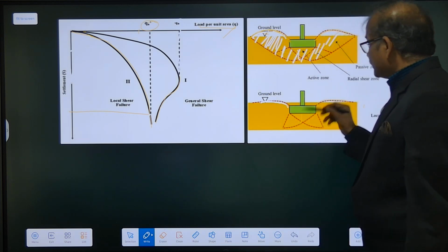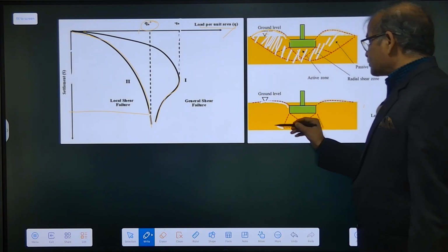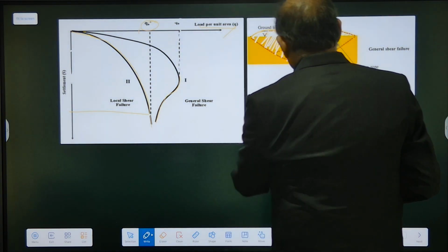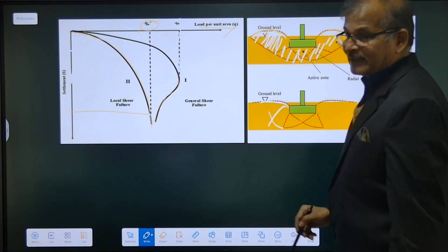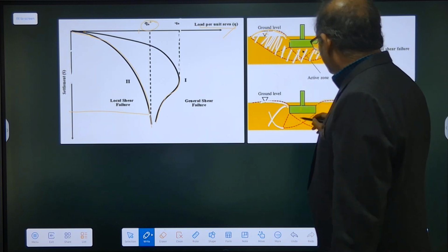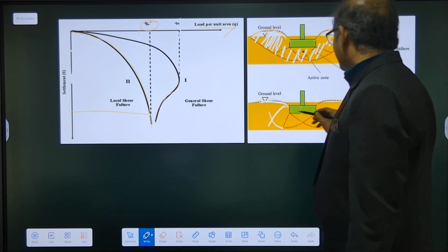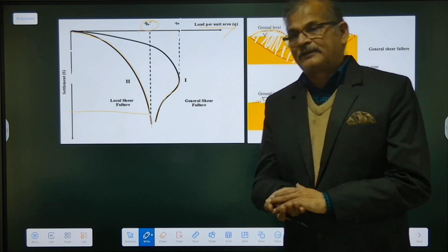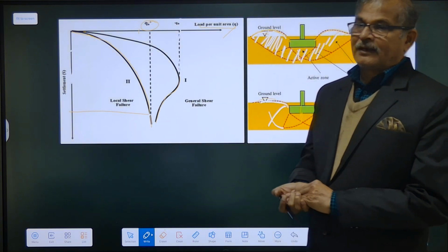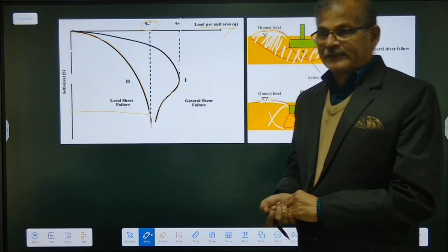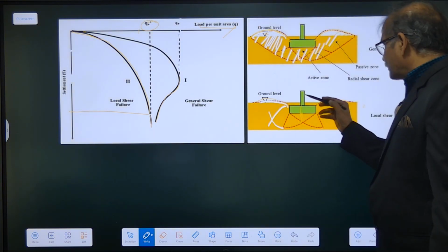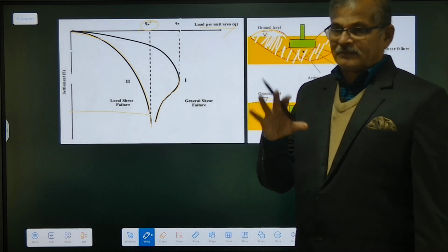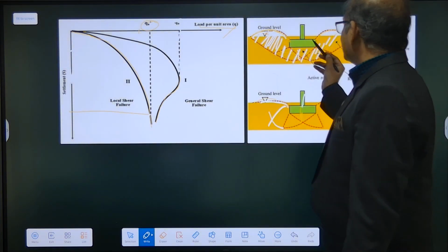But in case of local shear failure, जो soil का radial shear जोन है या confined पैसिव जोन है well defined नहीं होता है, सिंकिंग ज़्यादा होगी और बहुत स्मॉल बल्जिंग आएगी। इसका फेलियर ज़्यादा घातक होता है। With less load structure will keep sinking and there will be a lot of loss, even collapse हो जाएगा या कोई ह्यूमन का लॉस हो सकता है पैसे का इकोनॉमिकली।